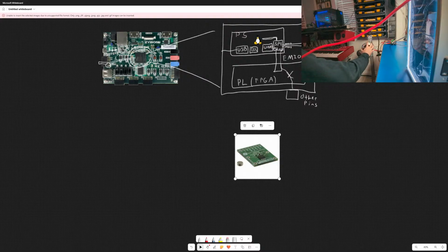I can't accommodate for that if I don't have a high enough resolution of an encoder. And the Hall effect sensors have a really crappy resolution. I can't remember what it is off the top of my head, but it's definitely not sufficient for precise robotic applications. I mean, after all, it's a hoverboard motor. It was made for having a person stand on a thing and then move forward and move backwards, right? You don't need a lot of accuracy with the encoders measuring the angular displacement of the motor. But for this, you do.